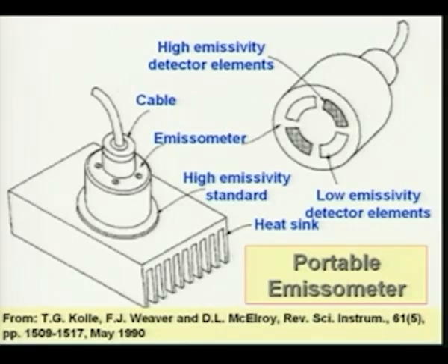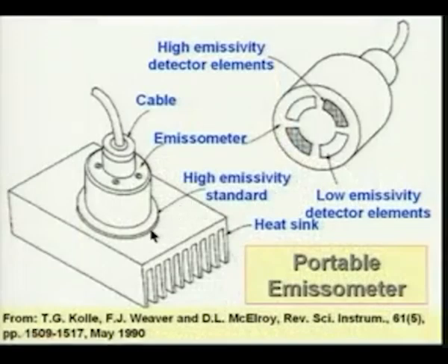Okay. So, what will happen if I have two objects close to each other? The heat transfer between the head which is heated and the surface of the sample which is not heated, which is presumably at room temperature, will depend on the difference in temperature to the power of 4, that is, T of the detector to the power of 4 minus T of the sample to the power of 4, and T sample to the power of 4 is a constant because it is going to be the room temperature.